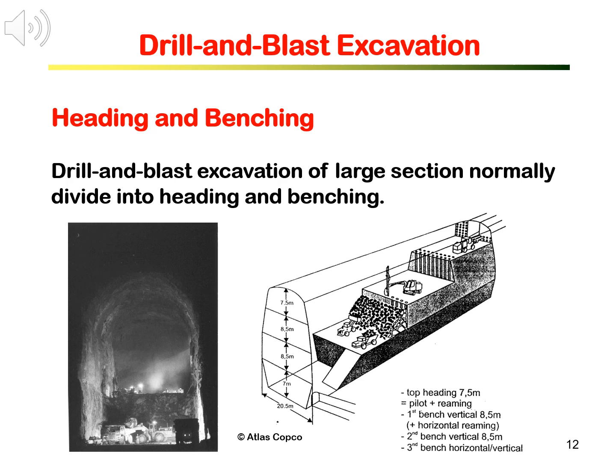For large excavation, such as a cavern, blast excavations are done in heading and bench. As shown by the figure, drill and blast excavation of large cavern sections is divided into heading and several benching.